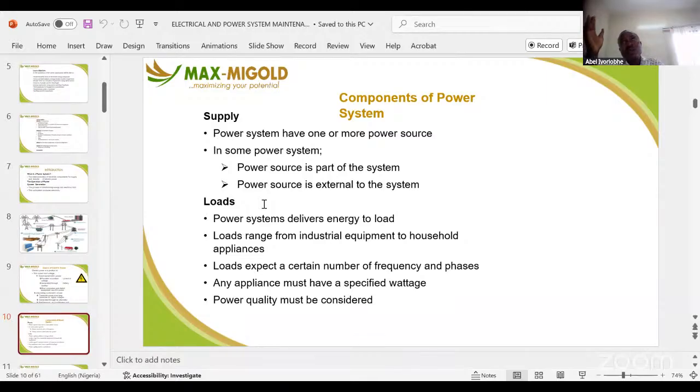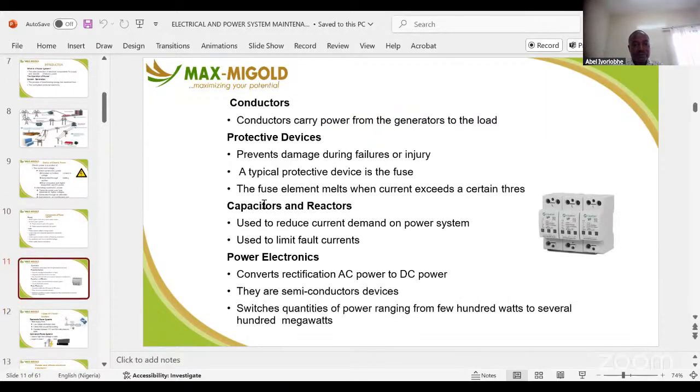Like a 10 kVA generator cannot take more than 2 AC. If you go and buy 2 horsepower AC, your 10 kVA generator may not be able to power 2 of them. But if you have 1 horsepower each, your 10 kVA can successfully power those 2. So that's why you need to pay attention to the labeling that you have on your equipment. So they play a significant role in our facility.